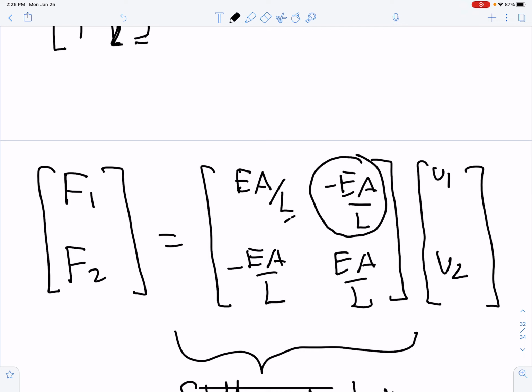Practically, and this is an important thing to note, we used the differential equation machinery, applied general displacement boundary conditions, solved for the displacement distribution, applied the constitutive law to get the force state, used the force state to extract the nodal forces, and recorded them.